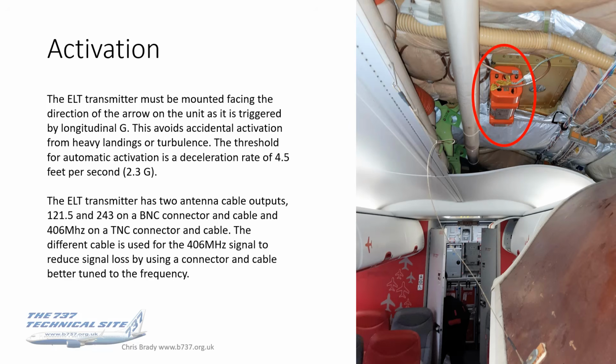Trying to relate this to something you may know, certainly the TV signals that come into your house. It's a different TV cable from a regular old-fashioned antenna to the satellite dish, and that's because of impedance matching. If you use the wrong impedance cable, then you'll actually get a reflection of the signal, and the signal will be attenuated. So they need to use the most matched cable to the signal, to get the maximum signal strength. And the more signal strength there is, the greater your chances of being found. Is the logic there.